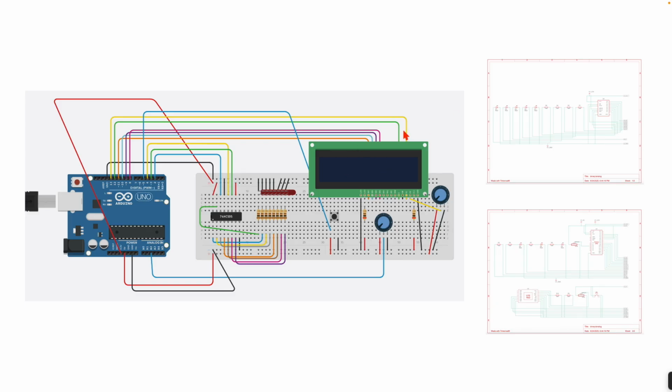It requires 6 digital outputs from the board, along with 2 grounds, and then 2 inputs of 5 volts, one put through a resistance of 200 ohms, and a potentiometer, which in this case isn't returning the value of its resistance to the board. It is returning the output current with the variable amount of resistance into the LCD, which is used to adjust the brightness of the backlight of the LCD and thus the contrast of the LCD. So to tune how the LCD looks, you can turn the potentiometer, which is very helpful.